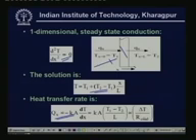delta T by R conduction, where delta T is the temperature potential which is driving the heat transfer, and R conduction is the conductive resistance. So this equation is almost analogous to Ohm's law. In Ohm's law for current, we write I as E by R, where E is the potential difference and R is the resistance. So this equation is also analogous to Ohm's law.